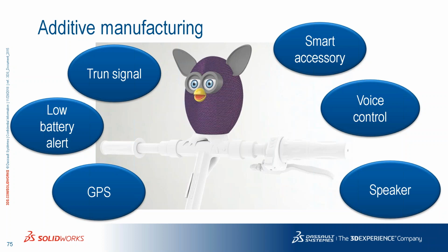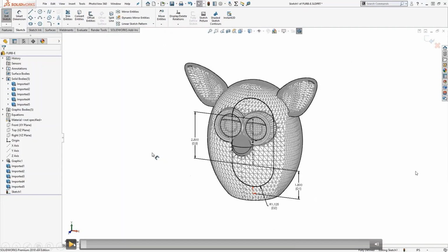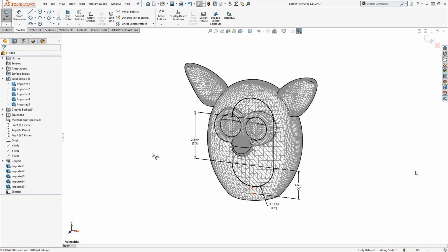So the model that was used by Urban 626 was downloaded, purchased from a site that offers this service. So in SOLIDWORKS, what was imported is this model that is a mesh. You don't need to rebuild the mathematical model from the mesh. You can just keep working with the mesh.